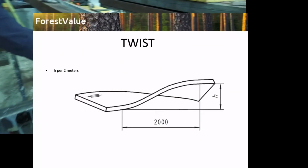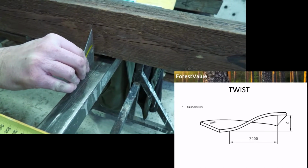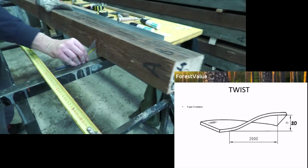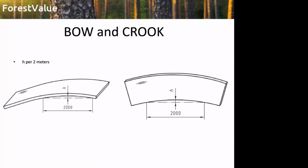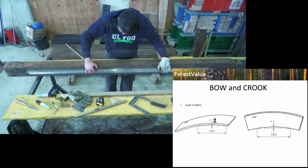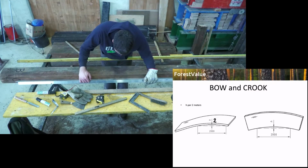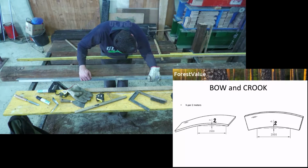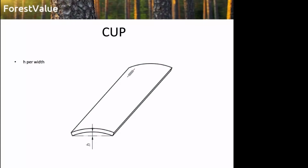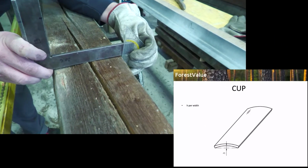As with new timber, we usually want our reclaimed timber to be straight. That's why we measure the twist of the specimen. This was measured in millimeters on a 2-meter length. The same was done for the bow and crook effect, with the help of a 2-meter long piece of aluminium. We also measured the cup in millimeters per width.